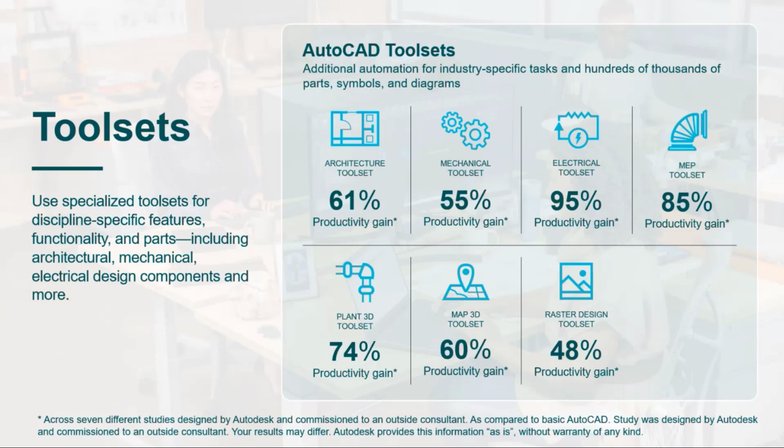Here, Raster Design is one of the most potential features because it is not an industry toolset, but an industry technology. If you are working with any specific toolsets, or with any legacy drawings, Raster Design plays a major role. It gives you a major highlight. How can we convert our image files into drawing files, how fast can you convert your grayscales into the layers of AutoCAD, and the patches are cleared automatically.